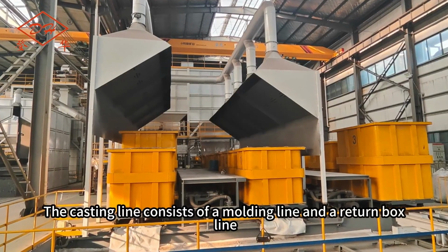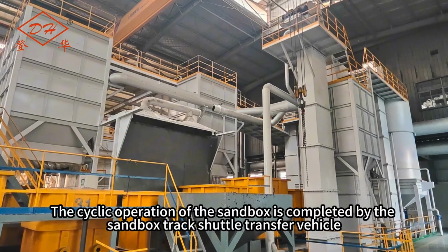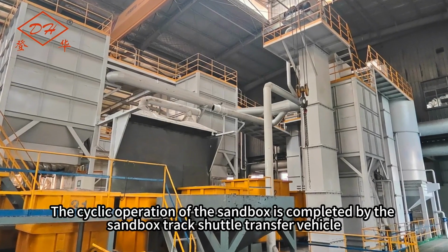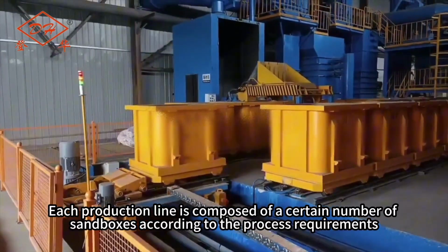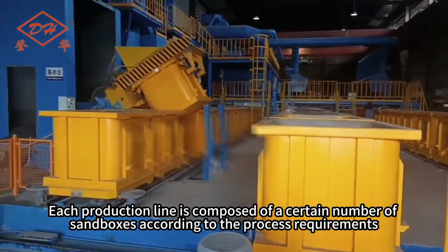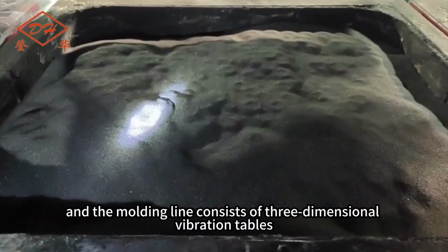The casting line consists of a molding line and a return box line. The cyclic operation of the sandbox is completed by the sandbox track shuttle transfer vehicle. Each production line is composed of a certain number of sandboxes according to the process requirements, and the molding line consists of 3-dimensional vibration tables.